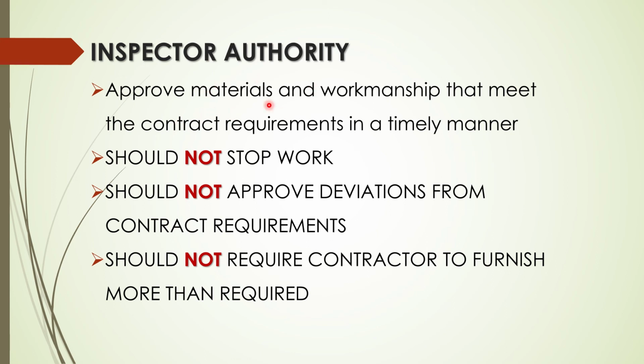Inspector authority. Approve materials and workmanship that meet the contract requirements in a timely manner. Should not stop work. Should not approve deviation from contract requirements. Should not require contractor to furnish more than required. Don't stop work, because that's a delay of work, and that's going to go back on the engineer.